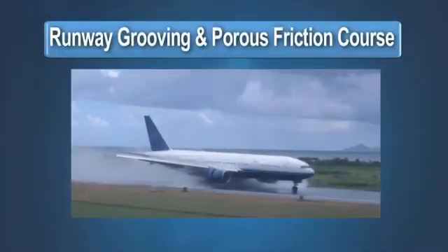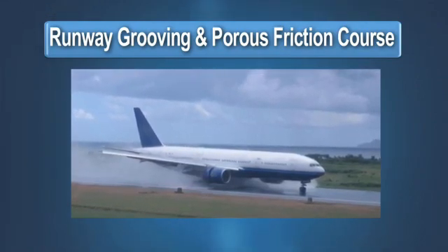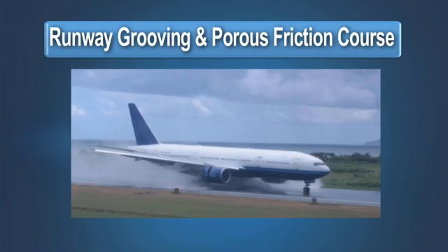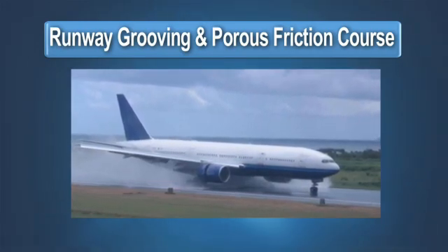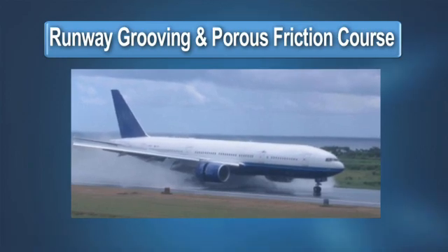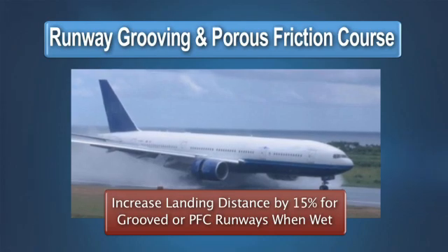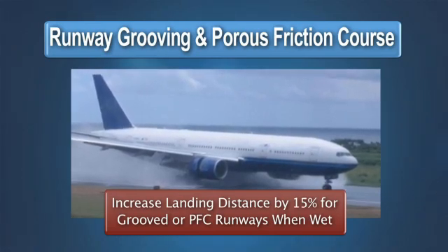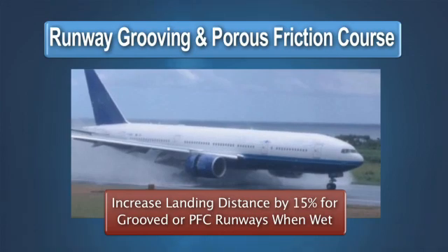A common misconception is that a grooved or PFC runway is considered to be dry for the purposes of applying the 15% increase when the weather reports or forecasts indicate that the runway may be wet or slippery at the time of arrival. Unless otherwise approved by the FAA, if the weather reports or forecasts indicate that the runway will not be dry at the time of landing, then the 15% increase to the factored landing distance must be applied.